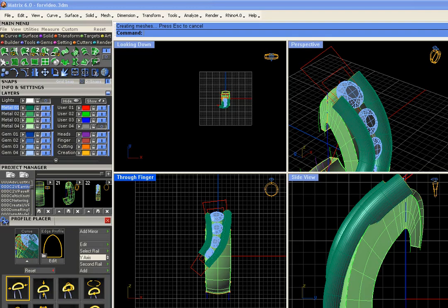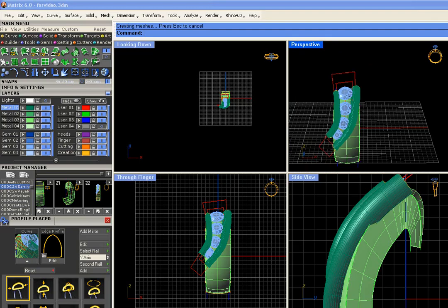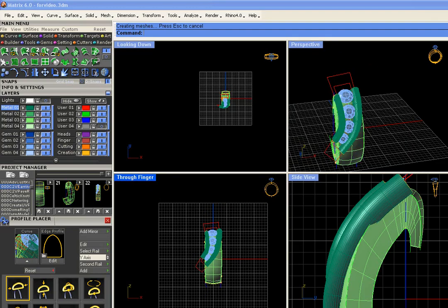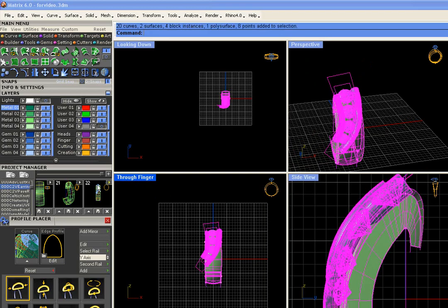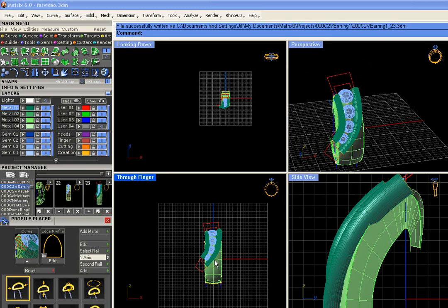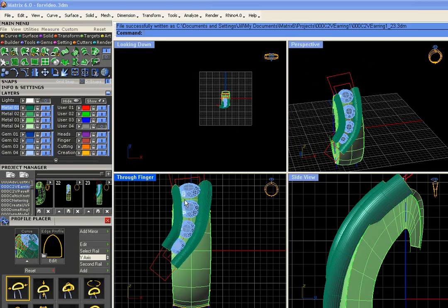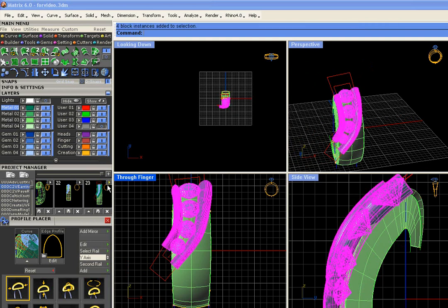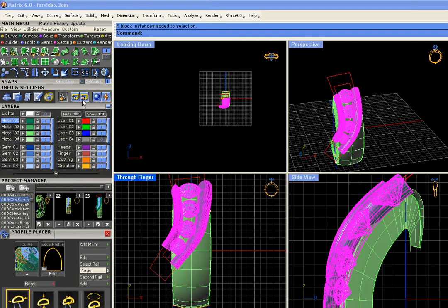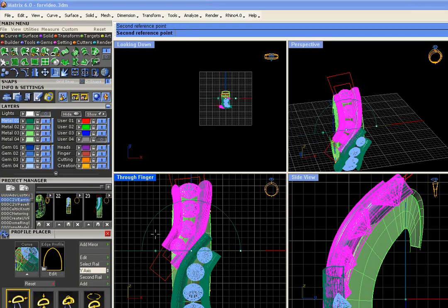Now, we're going to select the whole kit and caboodle here and rotate and copy it to the other side. But I've got a little trick for you first, and this is the real heart of the tutorial here, something we haven't really seen yet in our version 6 examples. So we're going to grab the surface, the gems, we're going to turn off matrix history and turn on rhino history. Okay, we're going to rotate this with copy, F4, shift, and click.